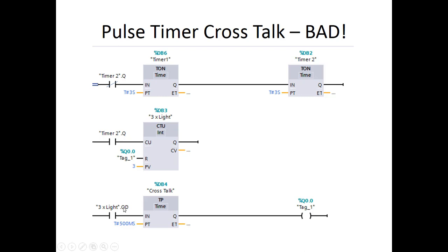Okay, so this is going to have a lot of problems because you were accessing the timer and counter data bits directly throughout this program, causing a lot of instantaneous reset of the timers and counters, and people were having a lot of problems.